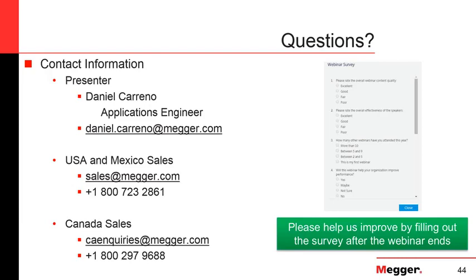Yes, like I said, if you remember, the ASTM standard says for you to have really accurate results, you have to put your potential leads at least 1.5 times the circumference or the perimeter of the conductor you are testing away from the current probe.